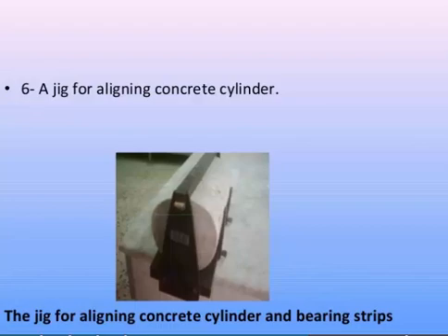Students, the tamping rod also has certain specifications, and it is used for the manual compaction of the concrete specimen. It shall be a round, straight steel rod with the tamping ends rounded to a hemispherical tip of the same diameter as the rod, and the diameter is 16 mm and the length is 600 mm. Basically it is used to compact the concrete, as when we are filling up the cylindrical mold, it is filled in layers. So tamping is required with the tamping rod. Then concrete pouring and compaction.